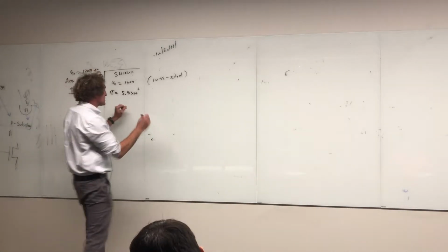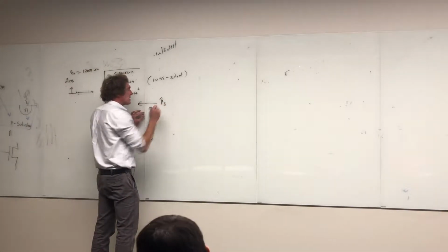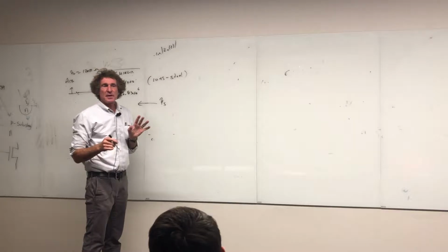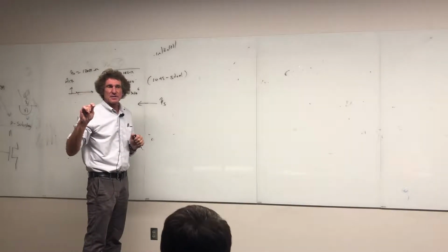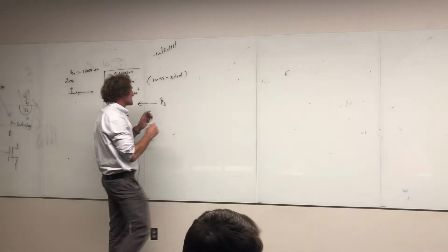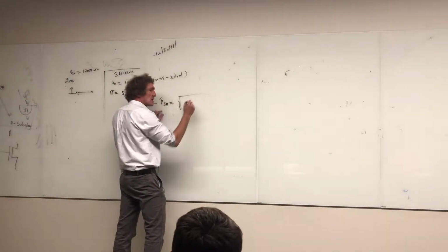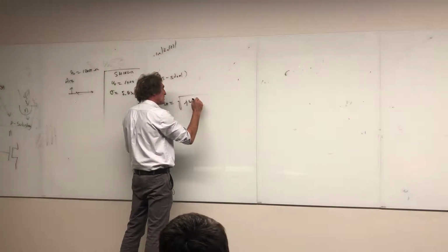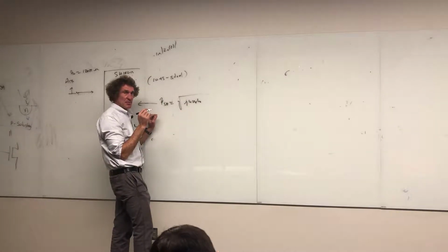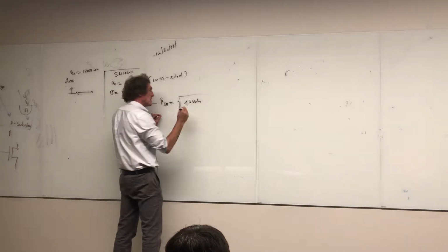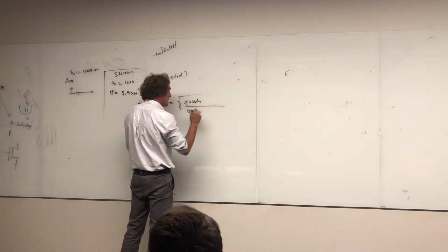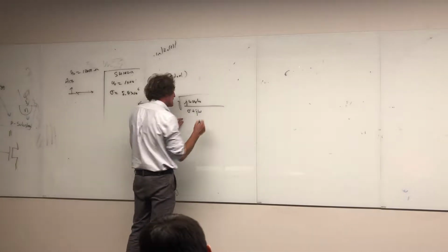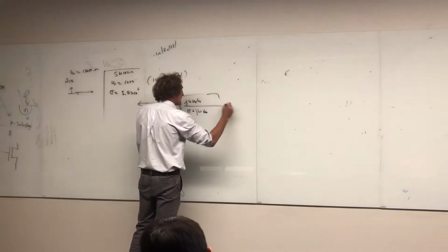So when we look at eta shield here, I mean, we can actually do the whole formula for this. You have calculators and that can do this. Does anybody have this on like a MathCAD thing where you can just plug things in and out of a formula? Well, I know eta shield technically is equal to the square root of j omega mu relative mu naught. Now remember, mu relative is 1,000 and mu naught is 4 pi times 10 to the minus 7. Divided by sigma plus j omega epsilon relative, which for steel is about 1, times epsilon naught. So that's it.